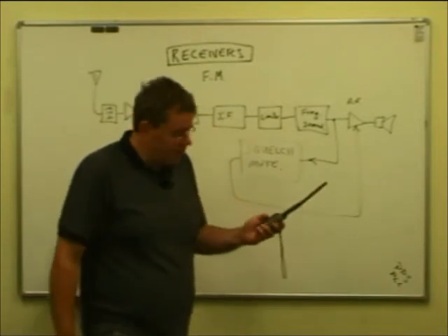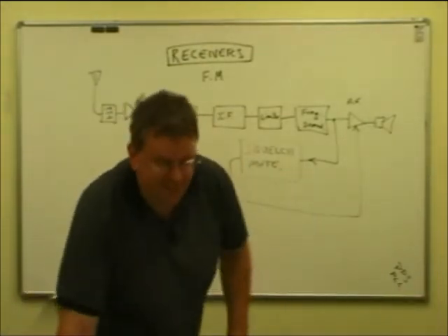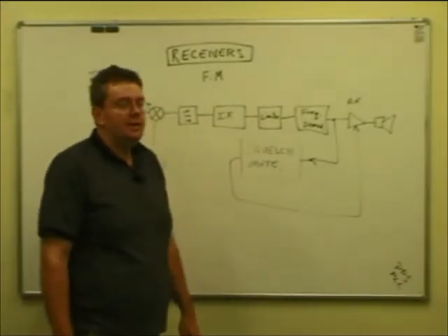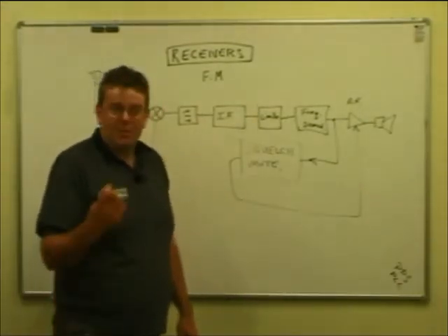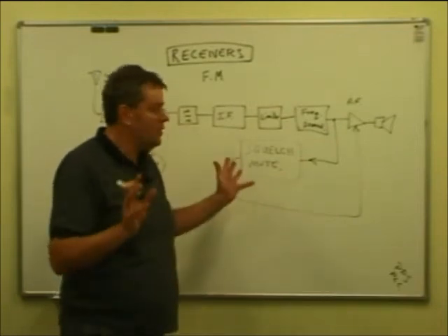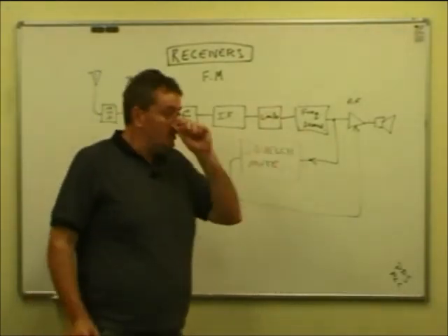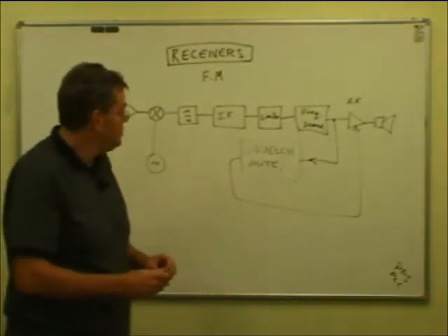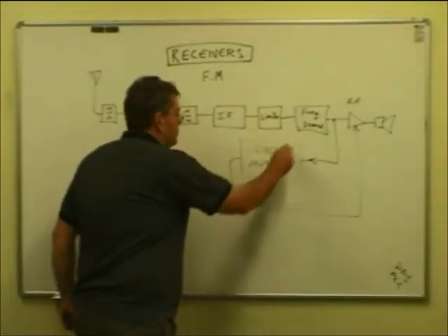And that noise at the end was the carrier dropping out, so the nice clean carrier signal with no noise on it. And just as the works are switching off, you get a bit of a burst of noise coming through as the carrier drops out and the system recognises it's noisy and shuts it down. You'd be very fatiguing listening to an FM receiver all day without that system. So that's a mute, and it's generally adjustable.